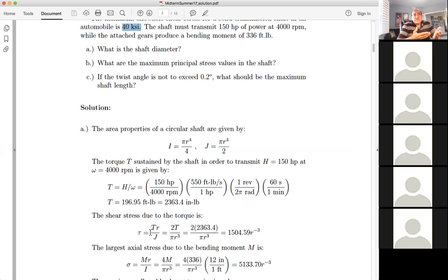The problem with this is that we do not consider additional aspects that can lead to overstress. And that aspect is that when we attach gears, as you'll see in the project, the gears produce forces either down or up on the shaft, transverse where they are attached.